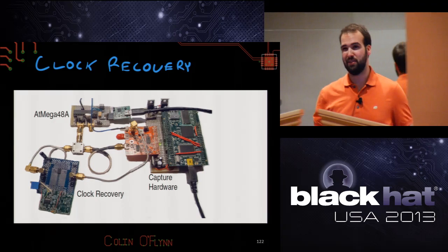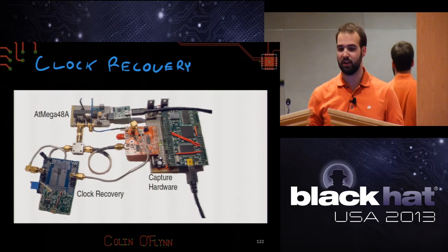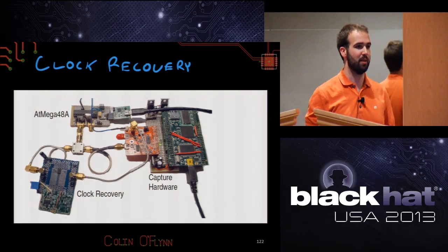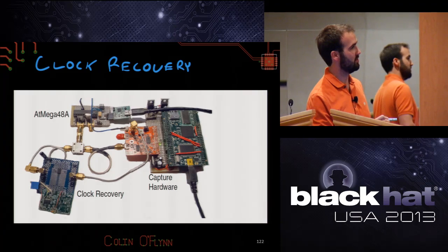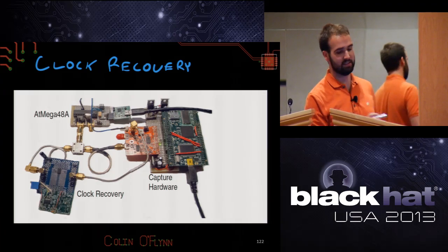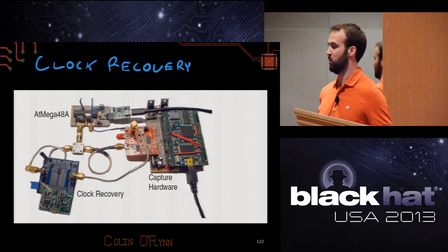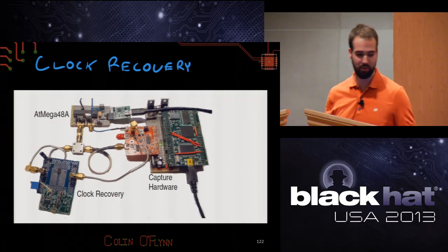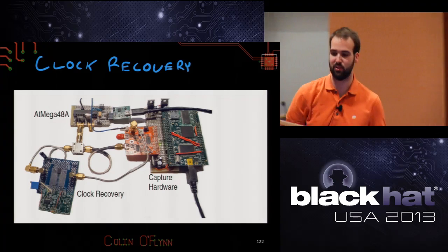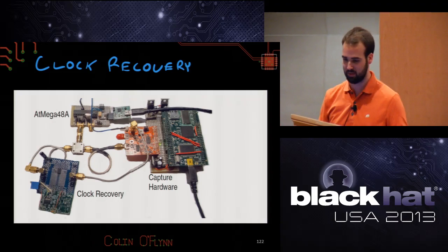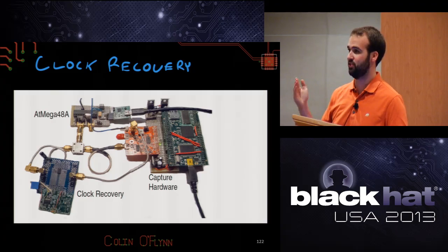This is pretty safe to assume for a lot of digital systems. Not all, because some systems may have internal oscillators inside the chip stopping you from tapping it. You can use a clock recovery system, so I won't go into detail, but it's almost exactly like it's done in communications electronics. It's been known, again, 20, 30 plus years, this sort of idea. You can use that to recover the clock and then attack the system, and this works quite well, even if the clock changes during operation.